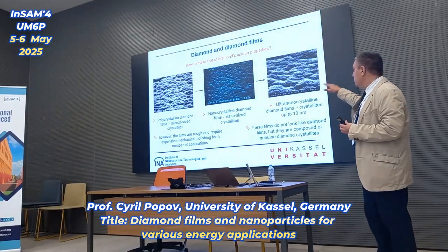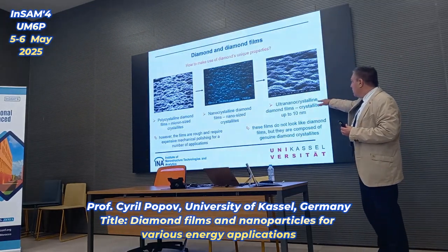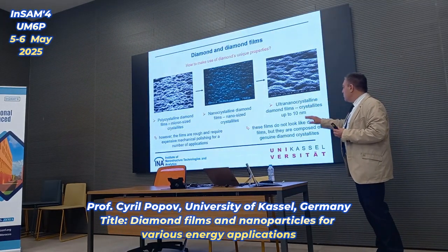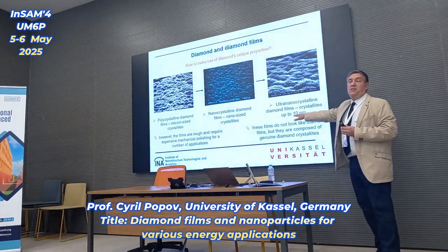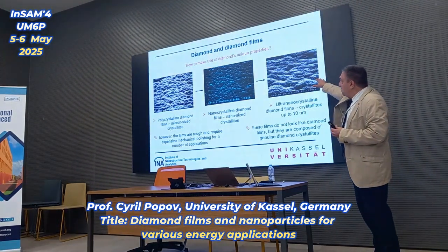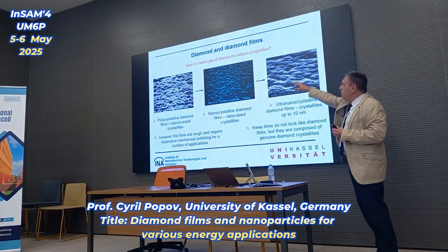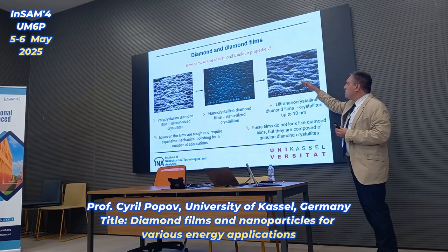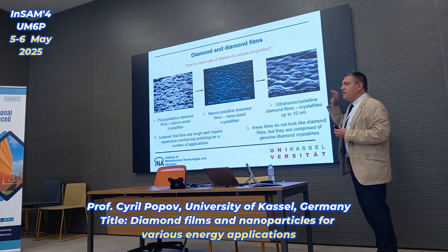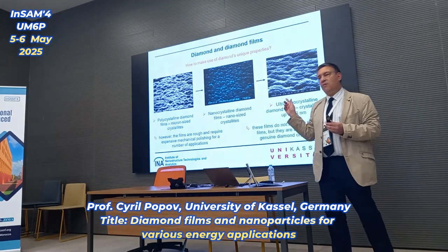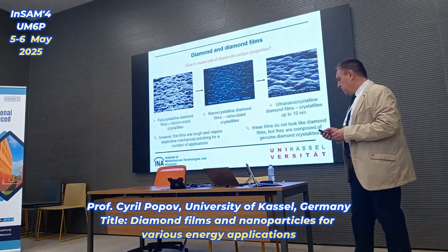Going in the same direction, we can come to the ultra nanocrystalline diamond films with crystallites up to 10 nanometers. These films now don't look like typical diamond films. You don't see the facets. However, they are diamond films, as I will demonstrate to you in a few minutes.